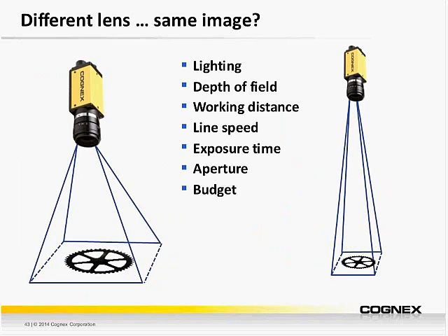For example, if you have some sort of robotic arm that's moving through an area and you want to protect your lens and camera from it, or maybe you need some extra working distance to make room for a special external lighting fixture between the camera and the object of interest. Or in other cases, you may have to be incredibly close. For example, if you're retrofitting the machine vision system into a space-constrained piece of existing equipment, working distance can have a very large impact on the actual level of performance you can get from the system, as well as affect the cost of the lens you need to use.